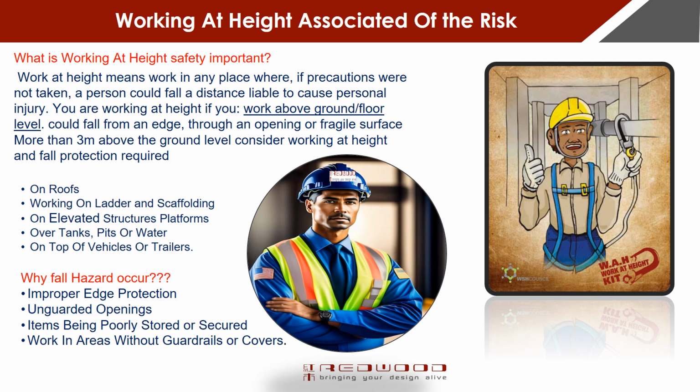All equipment, ladders, scaffolds, safety gear, must be inspected before use. Only trained and authorized workers are allowed to perform work at height. Work at height should be avoided if it is not safe to do so. All unsafe conditions must be reported immediately to the supervisor.